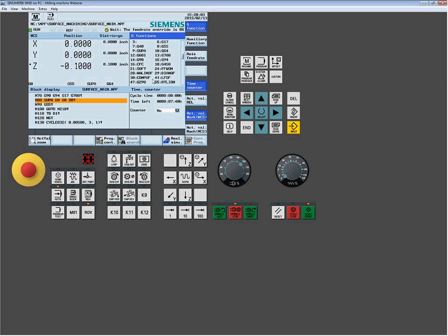So now I let the system in and start running. Now it's changed. One of the obvious things I'm going to see is G645 right here, so it's switched. Cycle832 is what's now automatically triggering a G645 corner rounding function. You don't have to know that.